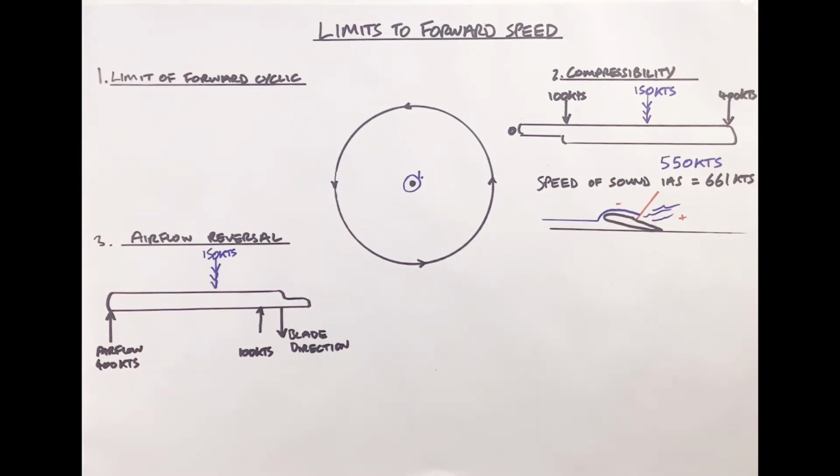So we're only getting 250 knots up on the tip, and unfortunately we're actually removing completely our generated airflow over the root, and we're replacing it with 50 knots that's moving in completely the opposite direction.